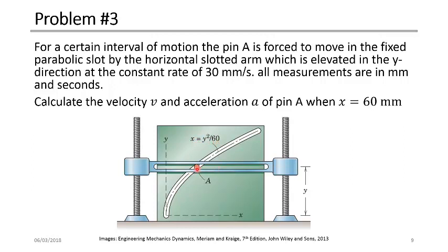And the pen here is controlled by the vertical motion of this part in the middle of this horizontal slotted arm. When we rotate these two screws, the arm goes up and down, and because the pen is here, the pen moves with the arm up and down. Because of the slotted arm, the pen can easily follow the parabolic slot on the vertical plate over there.